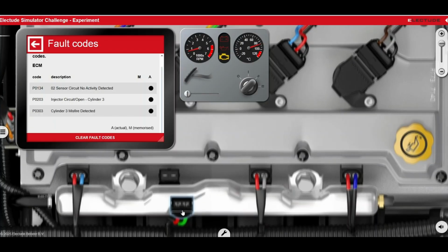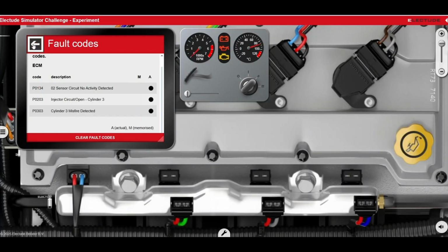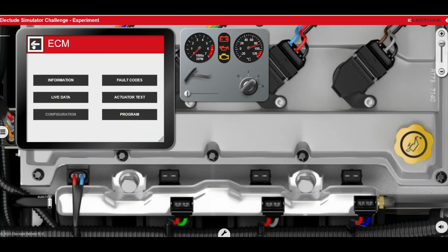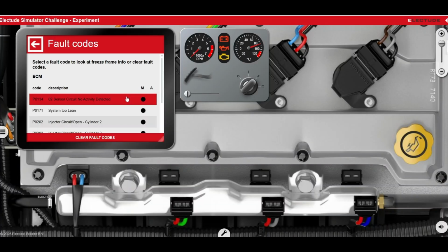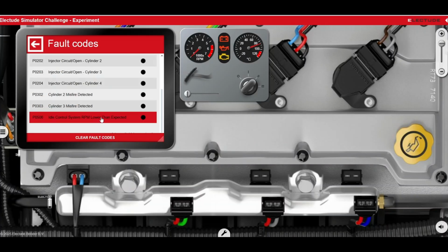If you disconnected 2 injectors, the misfire is worse. The engine is barely able to continue running. If I disconnect the third one, the engine will definitely die like it has now. And you are now going to have fault codes for misfire on cylinders 2, 3, and 4, and also injector codes for those cylinders. You can see the list of codes over there.